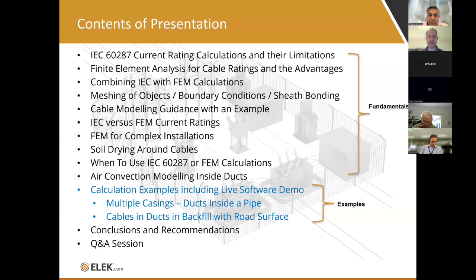FEM for complex installations. So we'll talk about where FEM must be used, and there are certain complex installations where only FEM can be used. Soil drying around cables, how you deal with that in the finite element method. We have a methodology for that.